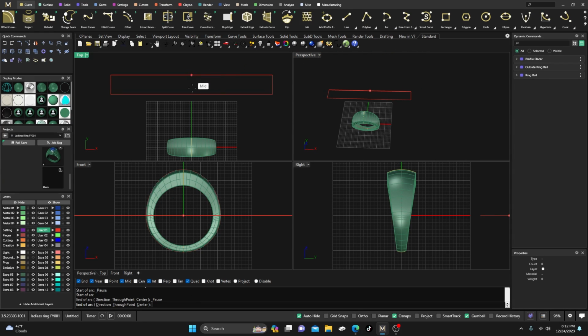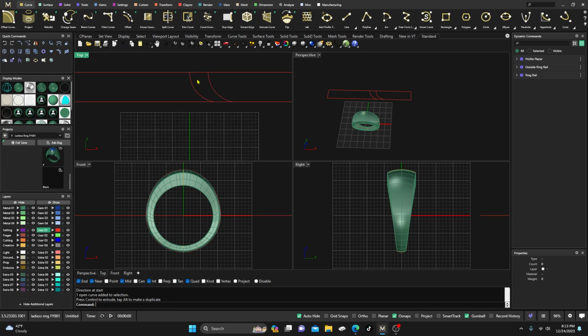I'll go to the mid, and I'll select over here with near snap, and then go like that. And I'll select on this, and then I'm going to hold down Alt and click on my arrow there and just drag it out, something like that. And I think you were trying to extrude these, and they were coming up non-closed or whatever.